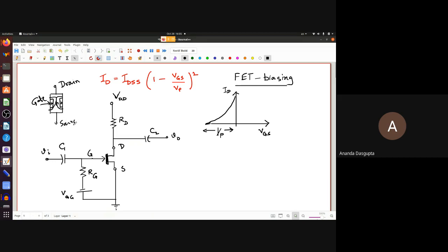And we have found that there is something called the Shockley relation, which relates ID to VGS. So this basically says, this is the value that ID takes when it saturates, when VDS is large enough. So this is the ID versus VGS graph. On the other hand, if you were to plot ID versus VDS, you would essentially get a graph which looks like this.